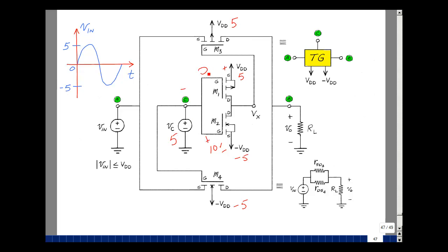Now let's assume that the threshold voltage for all these transistors is about 1 volt, just to make the algebra easier. Here I'm greater than threshold, and here I'm less than threshold. So you can think of this as a resistor that's going to be high or low, but since I'm greater than threshold, I'll think of this like a short circuit, and this like an open circuit. So the voltage here, if this was shorted, would be equal to minus 5 volts, and this were open. And again, this is an inverter, and that makes sense. Logical 1 in, a logical 0 out.